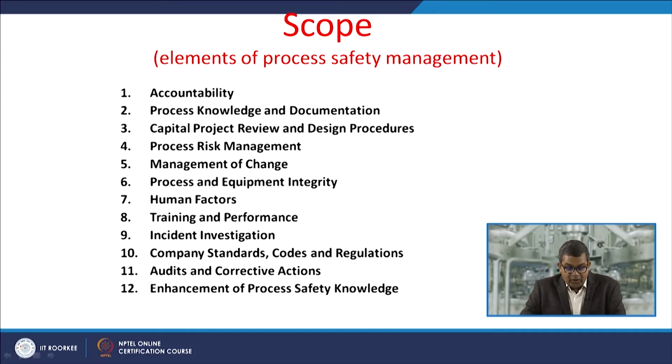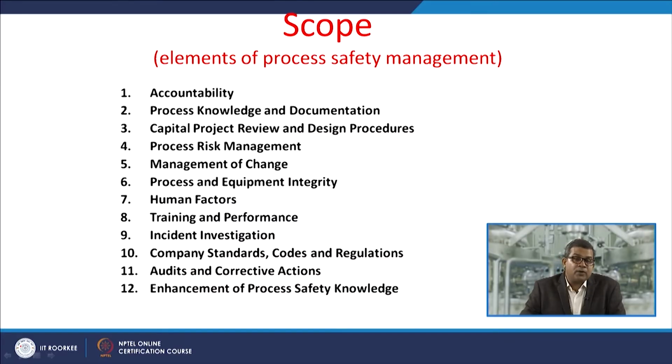You must adopt audit and corrective actions. You go for both internal and external audits, and in case any deficiency is found, then you need to go for corrective actions. You must make an effort to enhance process safety knowledge.